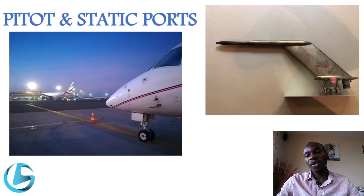Now this is a closer picture of a pitot tube, and I will try to explain what happens. A pitot tube has a pitot port here. As the aircraft moves forward, air goes in, and this is ram pressure that is indicated on an aircraft. The ram pressure comes from this pitot port, and around the neck of the pitot you have some small ports which are called static ports.